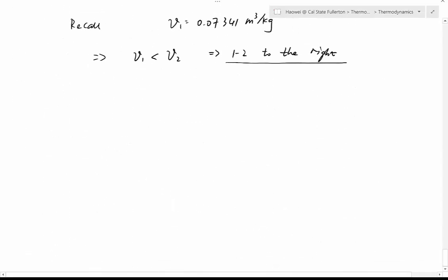To look for part 3, we start from mass flow rate. Mass flow rate is equal to rho V A. It doesn't matter which surface you look at, because mass flow rate is constant, so we're going to apply this equation to surface number 2 because we're looking for A2. So I want to have A2 show up in the equation. Do we have mass flow rate? Yes. Do we have V2? V2 is given. And do we have rho 2? Not directly, but something very similar.